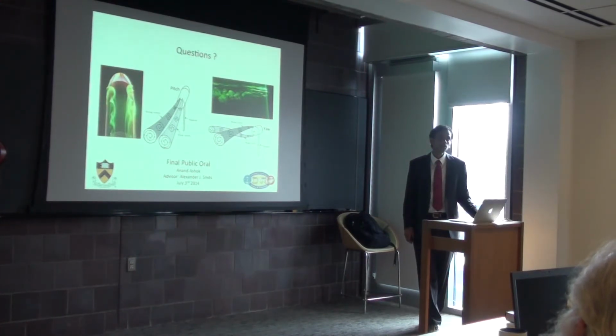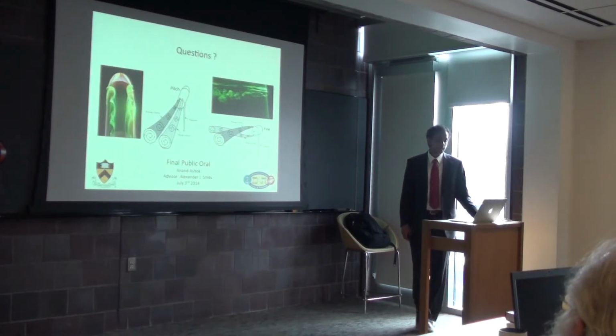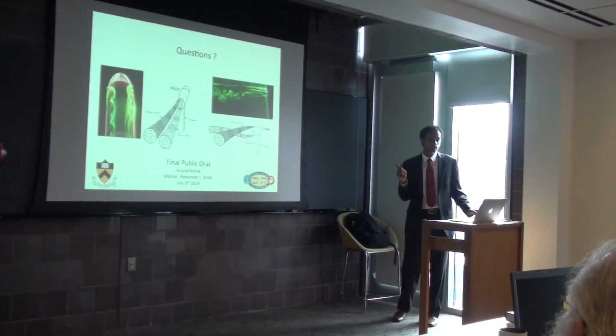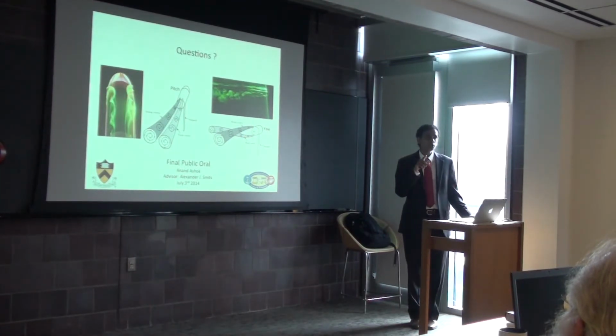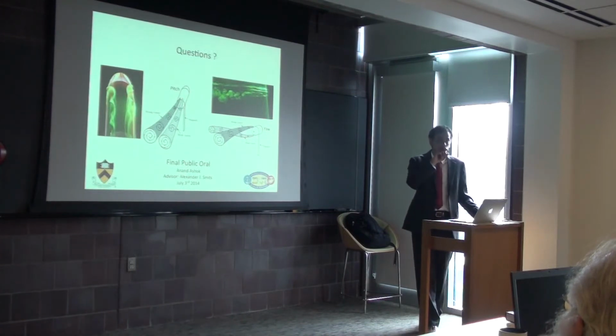If the submarine is slightly elliptical, or there's a twist in ellipticity because every lathe turns the same direction when it's being made, for example, there could be something tripping because there's a shape irregularity in your part. It's possible. I think that the disturbances that I subjected this wake to are much stronger in magnitude than what you suggest, and the wake wasn't sensitive to those. So I'm not sure that it would be sensitive to what you suggest.